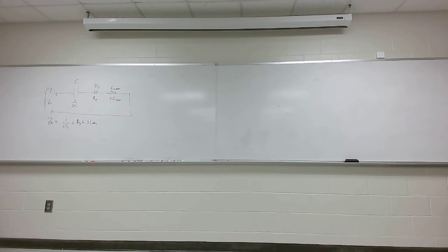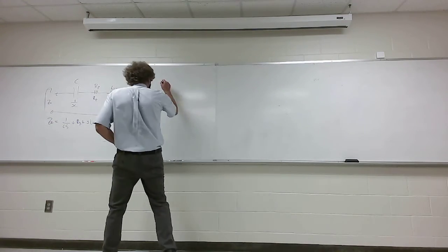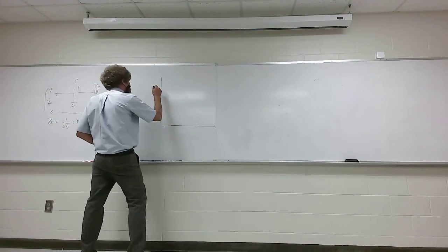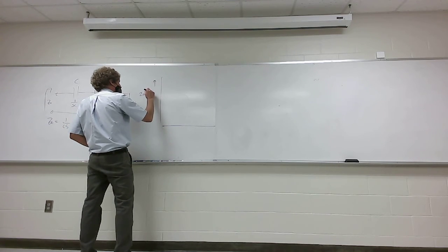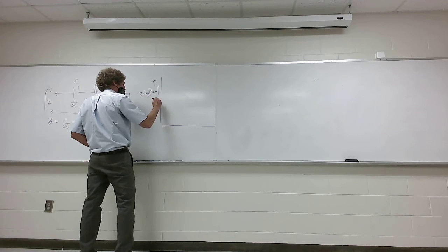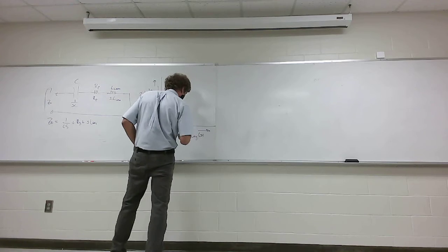He's got this on 515. He shows it. But here's how this works. When you talk about capacitive reactance, again, you're going to have 20 times the log of the magnitude of the impedance of the capacitor here, versus, and this will be the logarithm of frequency. This is a nice one to remember.